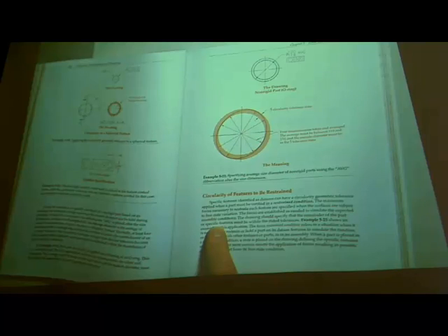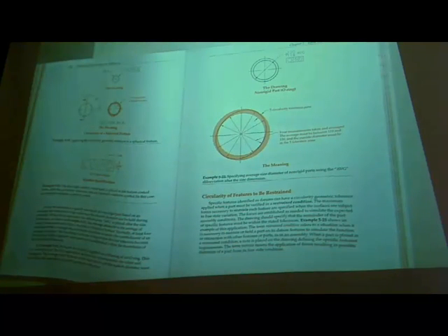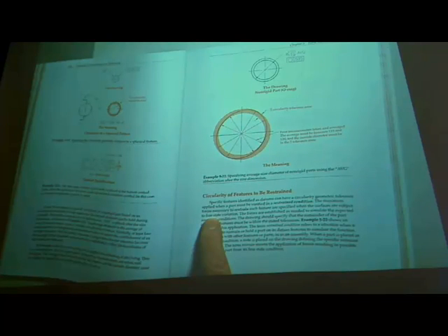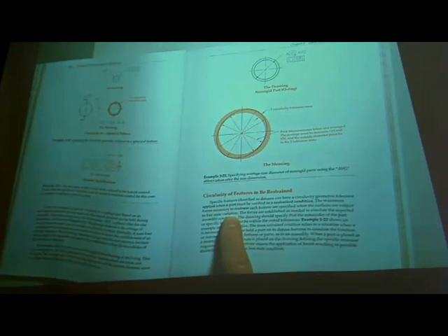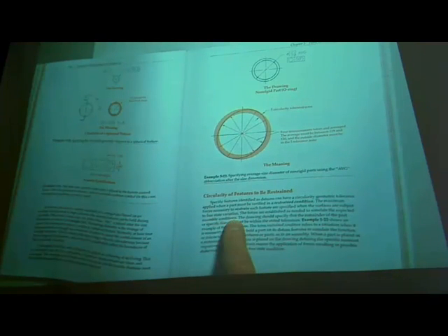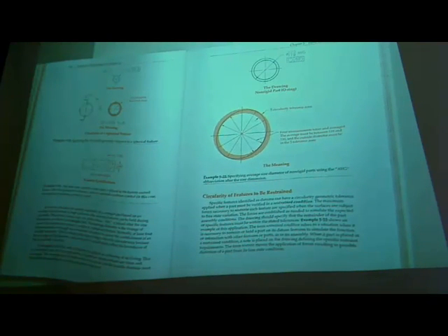So the maximum forces necessary to restrain each feature are specified when the surfaces are subject to free state variation. The forces are established as needed to simulate the expected assembly conditions.